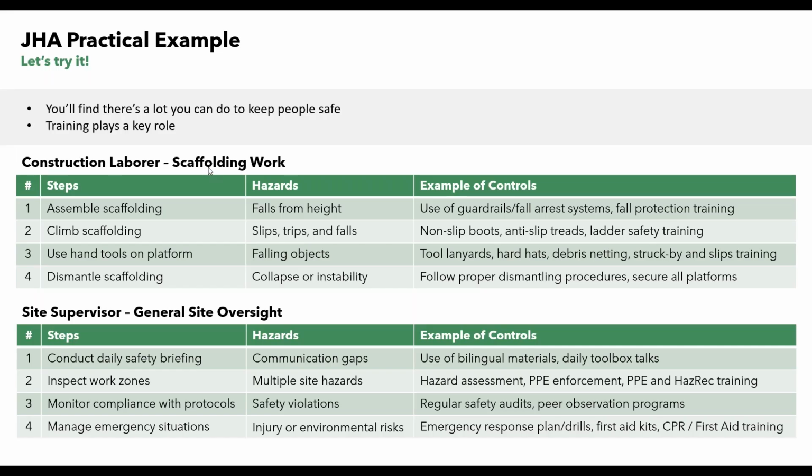And you can see the steps they're going through. First, they're going to be assembling the scaffold. So as you do that, there is the risk of falling from heights. You'll want guardrails, you want a fall arrest system, and of course, some fall protection training, as well as some scaffold assembly training, I would think. When you're climbing the scaffold, you want to make sure to avoid slips, trips, and falls. You've got non-slip boots. You're using anti-slip treads. Some form of ladder training is also probably appropriate.